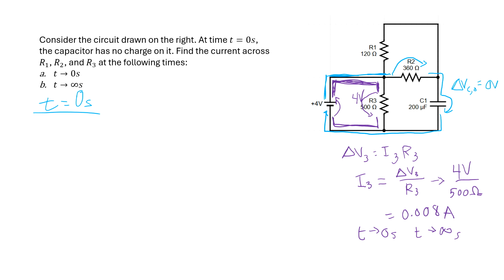No drop across a wire, because anything that's metallic is an equipotential. It has the same raw V value, so delta V is 0. In real life, there's a very small, few millivolts worth of drop across a wire, but in this theoretical case, there is no voltage drop across the capacitor if it's behaving like a wire.